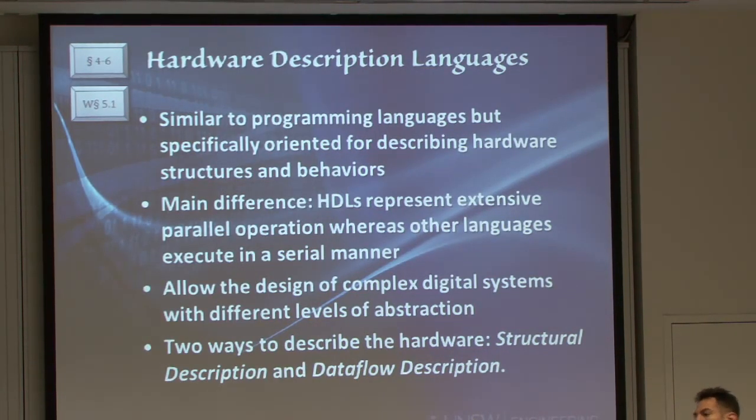Obviously, when you want to program hardware, that's not quite the case. When we program hardware, we have to remember that we're programming a parallel structure. Imagine that you have a few AND gates in your schematic or in your circuit. Then you evaluate the results of those AND gates continuously in time, and all of them are being evaluated all the time in parallel. You don't evaluate one of them, then stop and go to the next one, and then the next one.